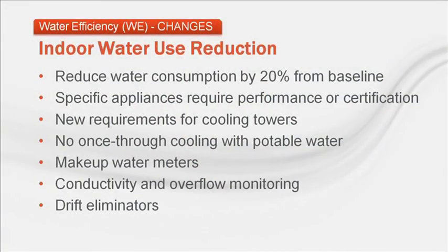The requirements are similar to those in LEED v3. However, there are 2 updates worth mentioning here. First, cooling tower water use is now addressed in the prerequisite. As a result, project teams cannot use once-through cooling with potable water. Cooling towers must be equipped with makeup water meters, and drift eliminators are required.